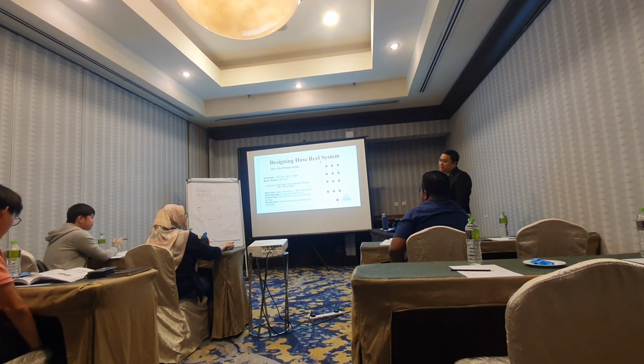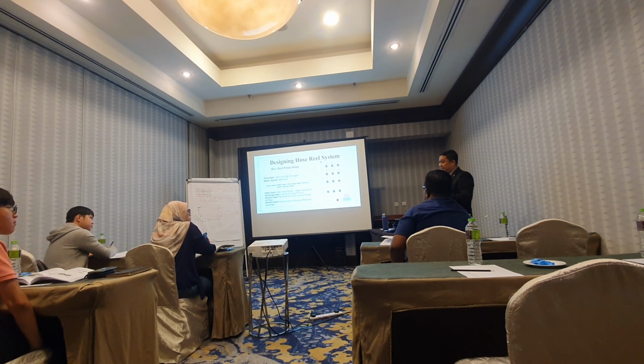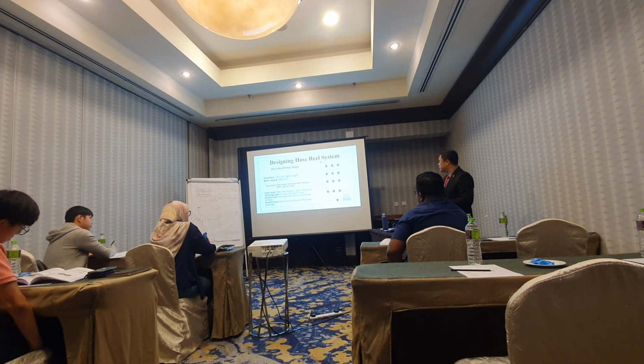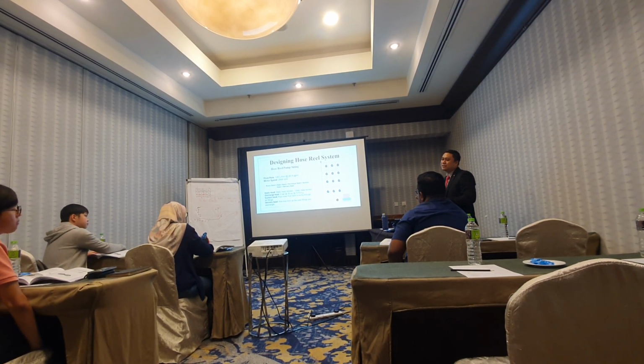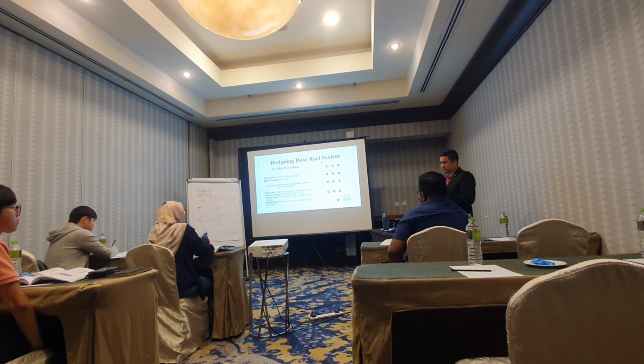It's a rule of thumb. How do you check? Normally engineers seldom teach this, because sometimes the rule of thumb has many other considerations. If the building height is 30 feet, the pump head must be more than 30 feet. If the building is 30 feet but your pump head is 25 feet, something is wrong with the engineer. Okay? Because you look at the static head delivery.